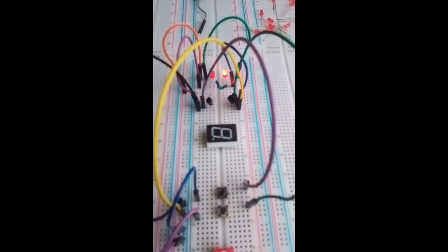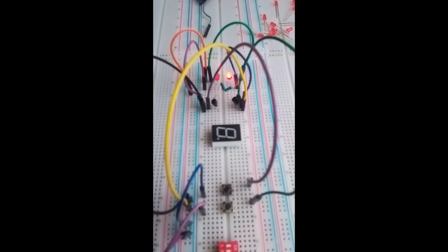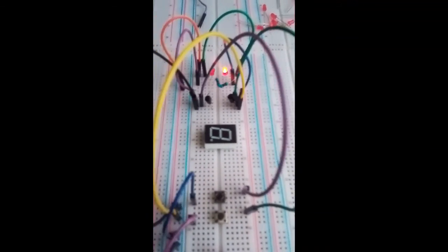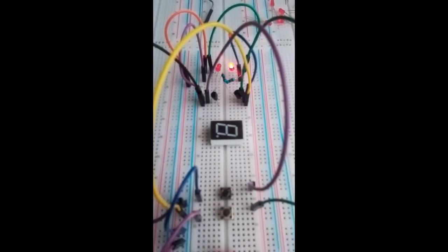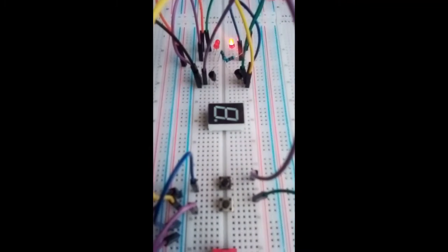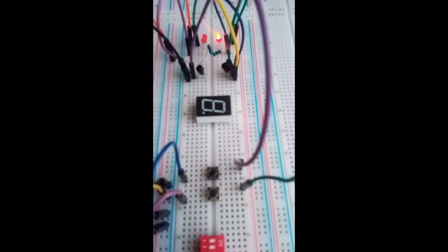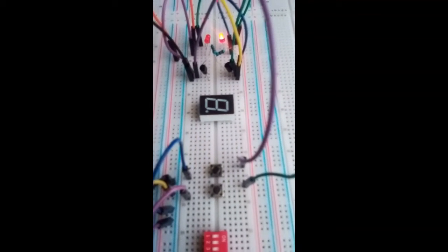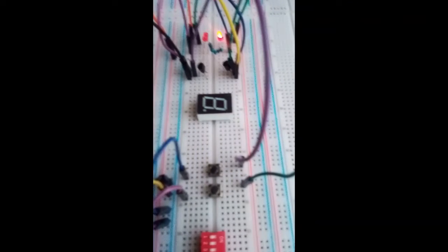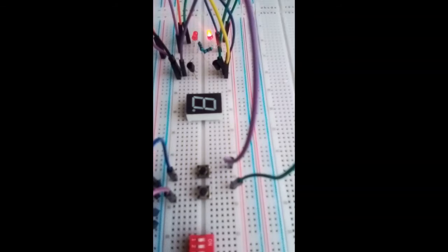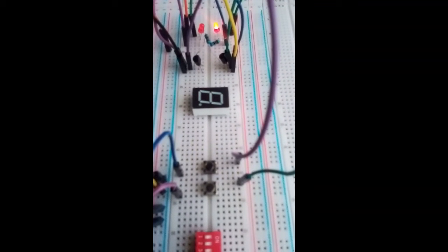In this circuit, I implemented two BJT transistors and two LEDs to demonstrate a latch. A latch can be set to 0 or 1. We can consider the output to be our right LED. Right now it's set to 1, and our input will be the switches. So the left LED will just represent the complement of our output, which right now is set to 1.